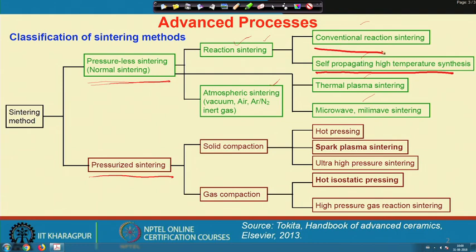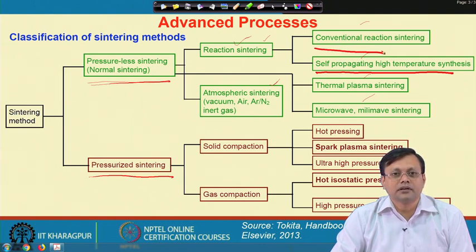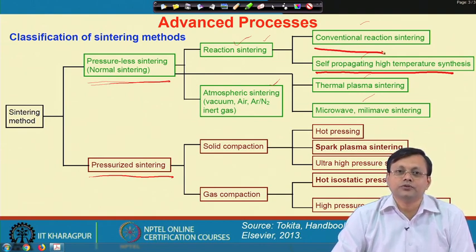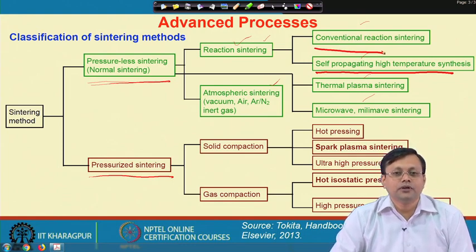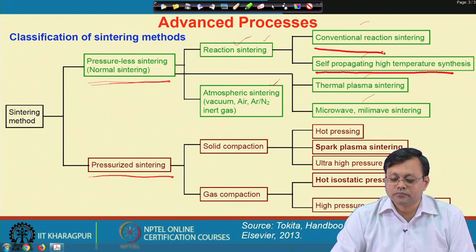Any reaction goes on. So, that is a typical conventional one, but let us say if you take some iron oxide and aluminum, Fe2O3 and aluminum, they can react together, and so it will basically make a self propagating type of synthesis. Once the reaction has started, you do not need further activation energy in order to propagate the reaction. So, this is one type of self propagating high temperature synthesis process. However, one should estimate how much calorie has been evolved due to the self propagating nature per unit mass and so on.